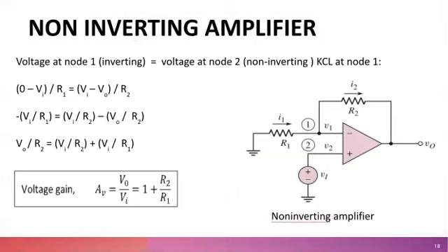Let's derive the non-inverting amplifier gain. For the purpose of our calculation, the input to the op-amp draws no current, as the impedance of the chip inputs, which is ideally Rin equal to infinity, will be well above the resistor R1 and R2 values used in this circuit. This means that the current flowing in the resistors R1 and R2 is the same.